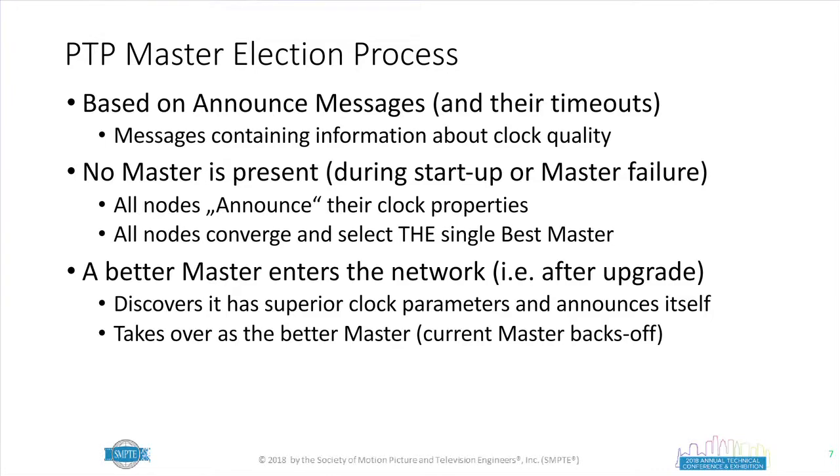What's important in terms of PTP is the election process. So it's based on announce messages and their timeouts. In order to have a coherent infrastructure, everybody needs to have the same values dialed in to all the devices. If you have some devices that are working with different values, you may have a system where the slave thinks it's timed out because it's not using the same announce and timeout values as other parts. This has actually come across in real-world implementations, so I always tell people the first thing to do is double-check if you have the same announce and timeout messages.